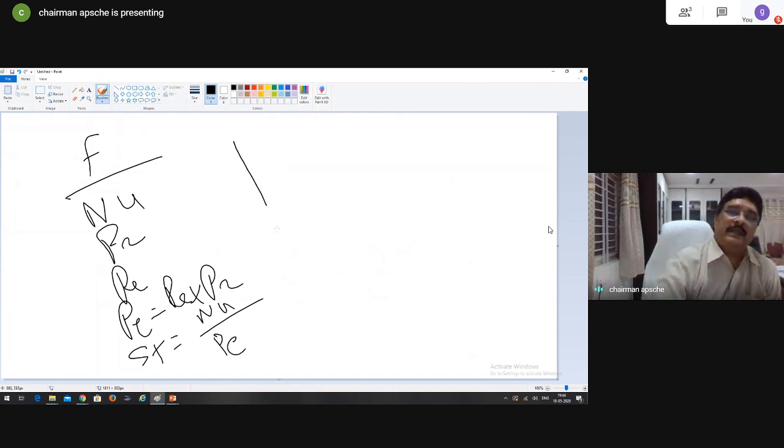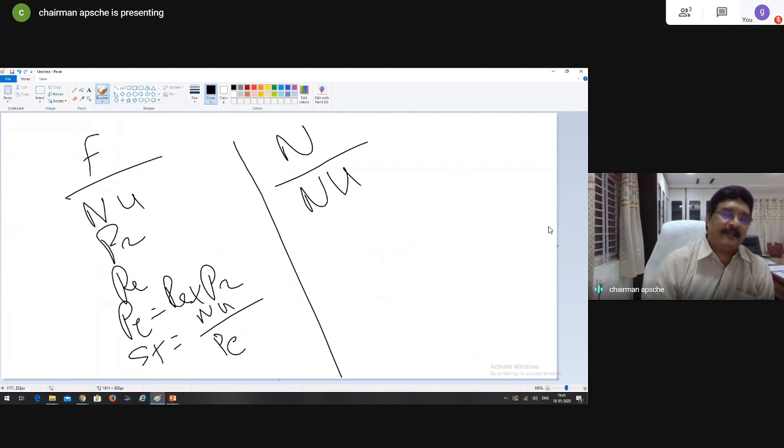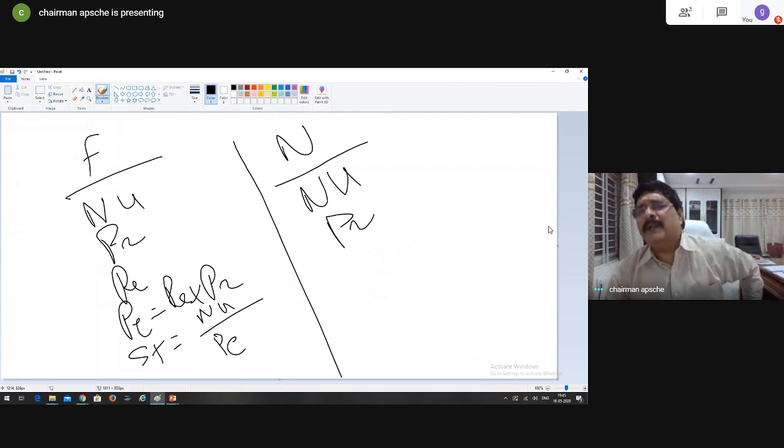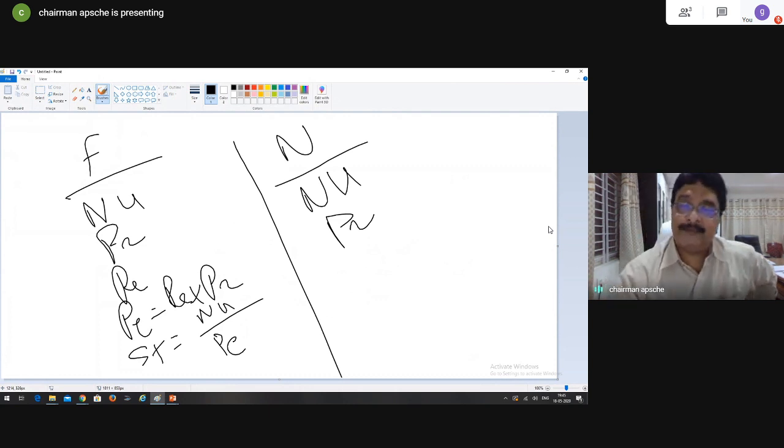In natural convection, we do talk about Nusselt number, because Nusselt number is the one which gives you the h value. So h is there for both forced convection as well as natural convection. And there is Prandtl number whenever there is a fluid, because it is purely based on fluid properties, mu, Cp, and k. Mu is a property of a fluid, Cp is a property of a fluid, k is a property of a fluid. Now the Reynolds number is replaced with Grashof number.